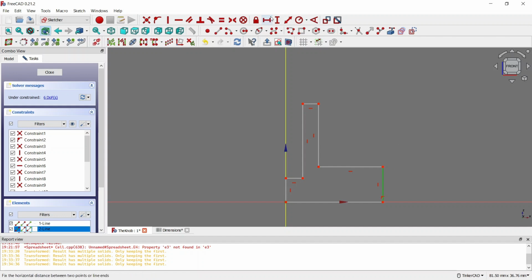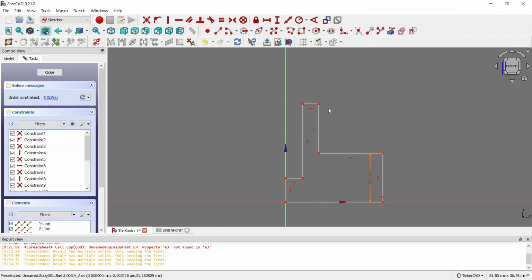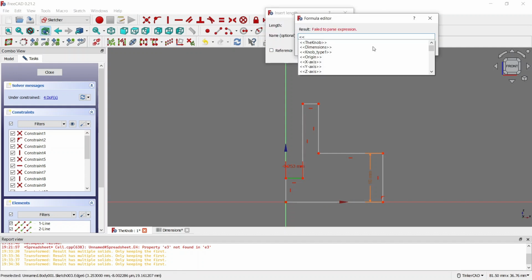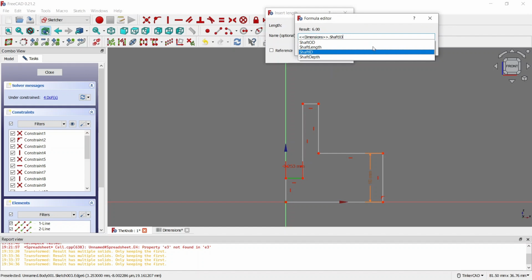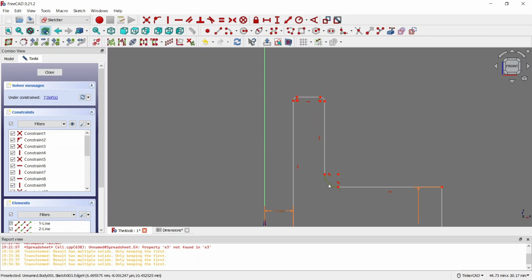Now we need to constrain those segments. So again, this is the knob thickness, and I'm drawing actually the part of the inside of the wings. So later on, well, here I'm constraining the radius of the shaft. I can also add chamfers already in here. And I forgot to draw them as lines, so they are arcs. I need to remove them and connect those segments with a straight line.